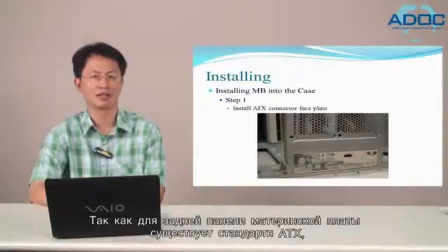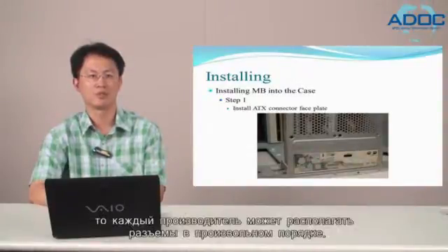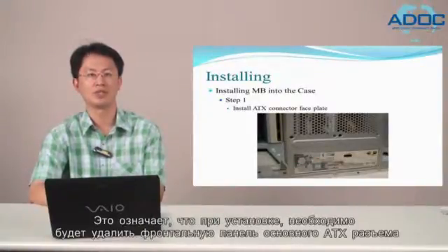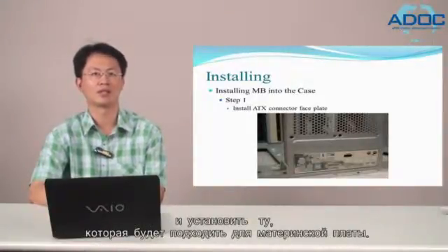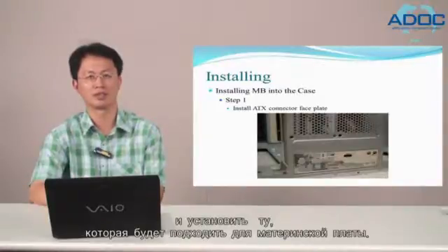While there is a standard ATX connector design for the back of the motherboard, each manufacturer can lay out the connectors however they need to. This means that the basic ATX connector faceplate will need to be removed from the case, and the custom one that shipped with the motherboard be installed.